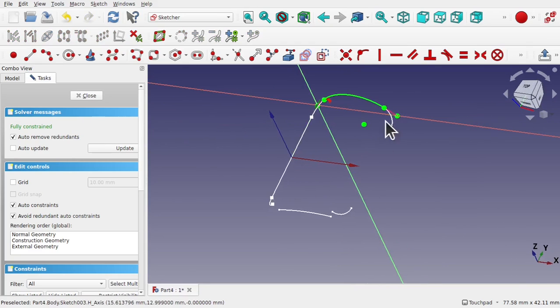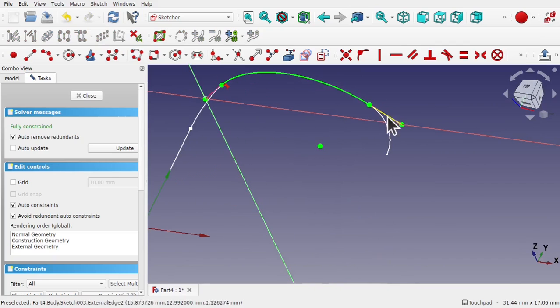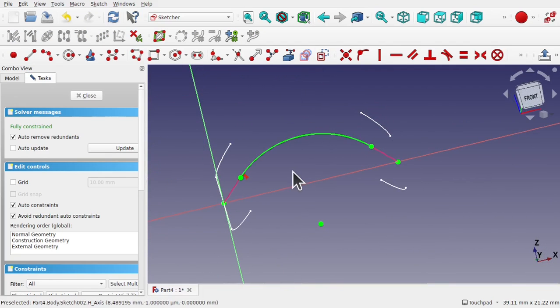The reason why this is not working is because of the angle and the length of those imported geometry. If we create an arc all the way through there, you'll notice that the arc will actually extend down below the line. So because we can't have tangency across both these lines, one way around this is to actually create two arcs. So I'm going to delete this arc and create another arc, and also another one.